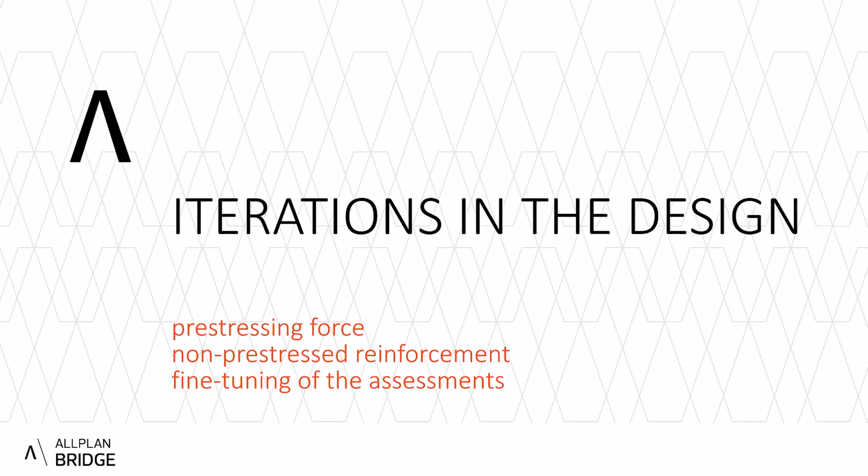In the following part of the presentation, we will iterate to refine the pre-stressing force in several steps. The design must be satisfactory at all stages of construction and operation. Afterward, we will perform the design of non-pre-stressed reinforcement and then we will advise on how to fine-tune the assessment of the stress limitation.